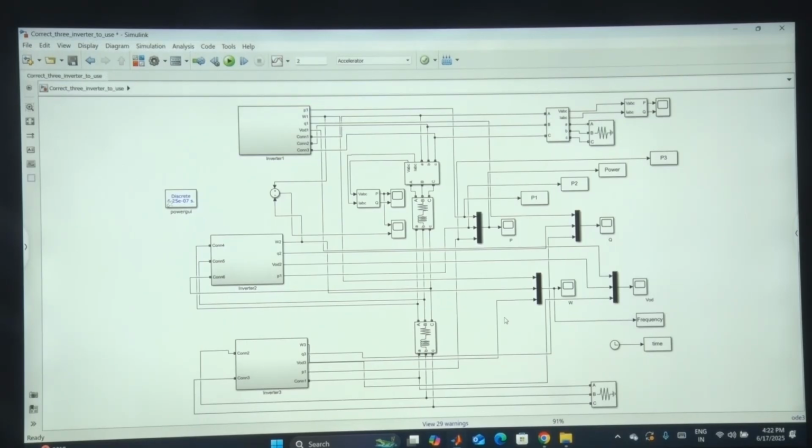Second thing is another very important one, which many people miss and then don't understand what is going wrong with their simulation. The sampling time that you choose and your system fundamental period, those should be integer multiples. Okay. So what happens if these are not integer numbers? What I mean is, for example, let's say you have a sine wave. You start with the 0 of the sine wave. Your sampling instant should be such that the next waveform 0 is sampled exactly at the same place.